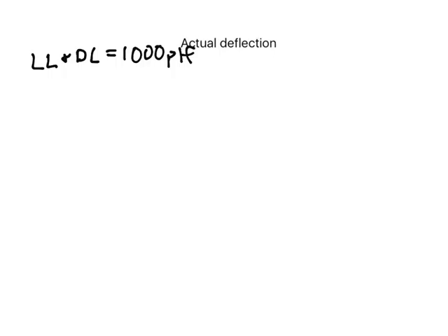So the next step, or the last few, the thing that we're going to do next is calculate delta max. This is the maximum deflection of that beam. And for an equally distributed load, the formula is 5WL divided by 384 times the modulus of elasticity of the steel, and then times the moment of inertia for the beam. So this formula is kind of interesting.